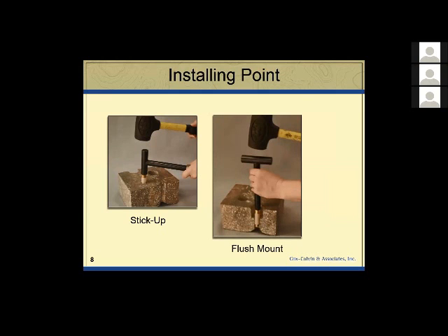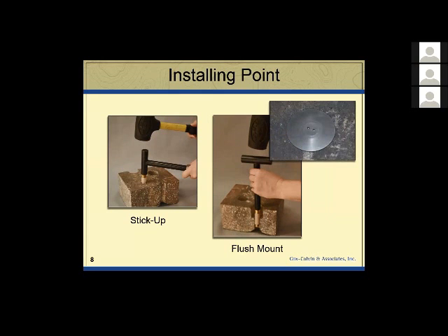If you're going to leave it there for repeat sampling, that would be more typical of vapor intrusion. The stick-up is more common if you're looking for sources, and once you find your VOCs, you pull them out and leave. If you're going to do repeat sampling, you drill a 1.5 inch hole and then a 5/8 inch hole through that, hammer the whole thing below grade, and you can screw this cover on the top of it, run over it with a forklift, walk over it, whatever you want.